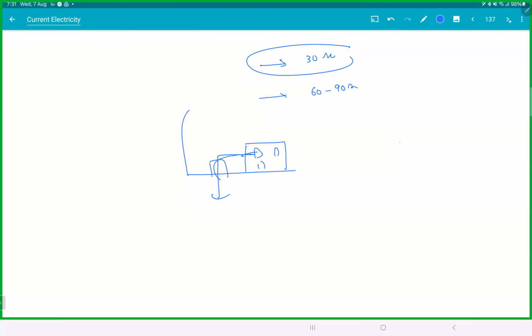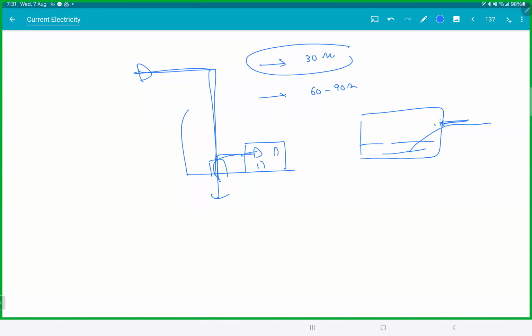But if you order any other flavor, the person has to go to the back of the shop, get the box, come and give it. It takes around 60, 90 seconds. So in this process, what is happening? The car had a problem actually. The engine, right? When you come to the place and stop the car, the engine is still heated. Because of the heat of the engine, the fuel is in a vapor state. It's called vapor lock. The vapor is creating enough pressure that the fuel is not going into the engine. It is not getting injected into the engine. But if you wait for a minute or 2 minutes, the engine cools down, the vapor goes off, and the fuel goes in.